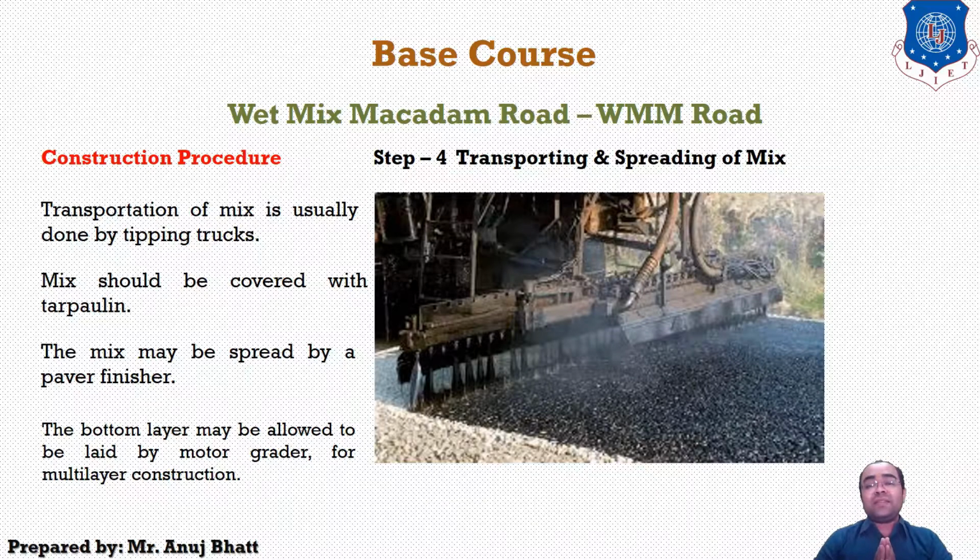Transportation of the mix is usually done by tipping trucks. To avoid moisture loss in transit due to evaporation, the mix should be covered with tarpaulin. The material is usually kept wet during transportation and laying to reduce the likelihood of particle segregation. The mix may be spread by a paver finisher. However, in a case of multi-layer construction, the bottom layer may be allowed to be laid by motor grader.